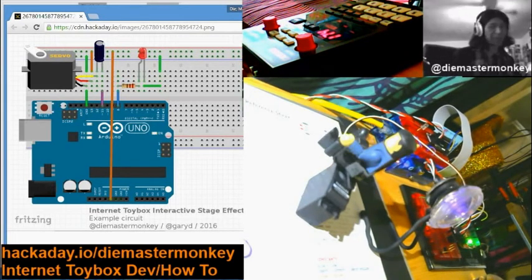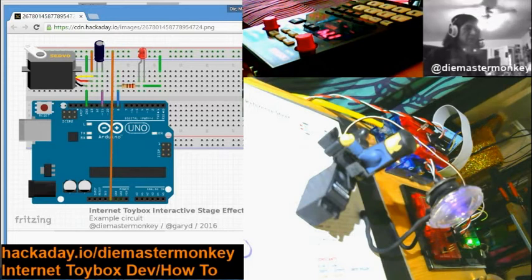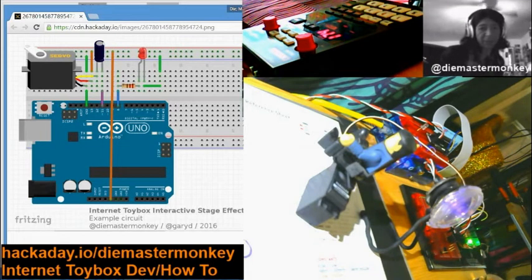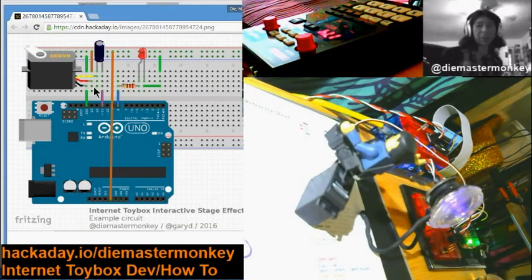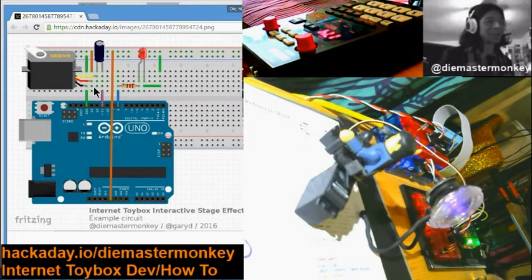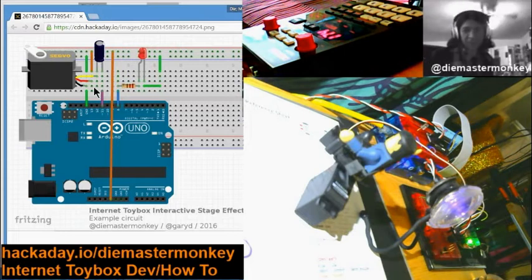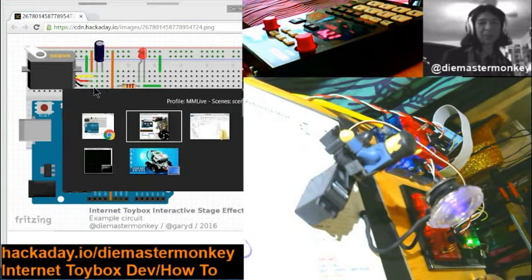So while I was off mic, what you saw me do is make the connections that you see on the left-hand side of this diagram from the servo to pin, where were we going? Took the signal off pin 11. I didn't use a smoothing capacitor. It's not really mandatory. And I'm not 100% sure why Spock is moving already. What is doing that? Very interesting. Oh, you know what? I do know what it is. There's some RGB code running on that pin, now that I think about it, and that's another story.